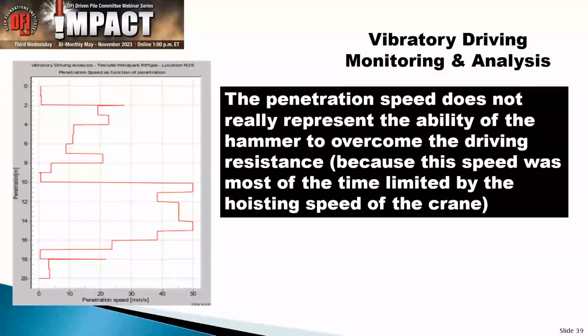And initially, quite often when you have a huge pile hanging there, crane operators are somewhat concerned. And they're basically saying, well, let's just play it safe. And they really hold it back quite a bit. And that sometimes is a problem, because if you don't give that pile that momentum, it reaches refusal much easier. So here, these numbers are probably not as realistic. There it went up, but again, you see here that it went down by about 20 meters. It just came close to refusal. So what is going on there? Because again, that is not what was originally predicted.